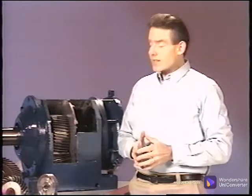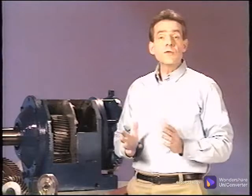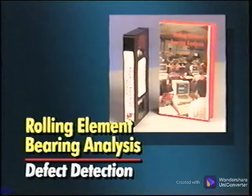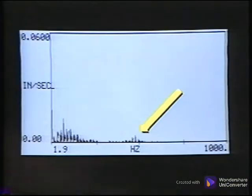Multiple reduction gearboxes, such as this one, can be more difficult to diagnose problems due to the additional frequencies generated. In another program on bearing analysis, we pointed out that bearing frequencies are defect frequencies and should not be present in a good bearing. Unlike bearing frequencies, gear mesh frequencies will show up at some amplitude, even if the gear train is in good condition.